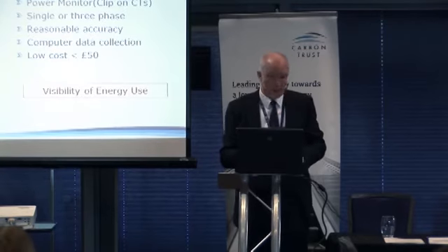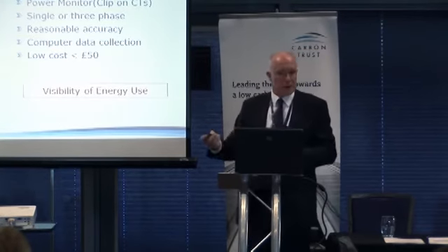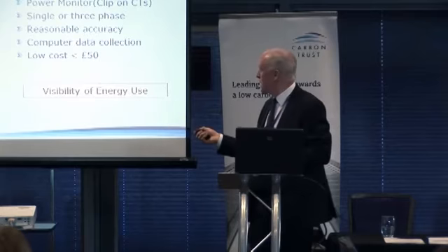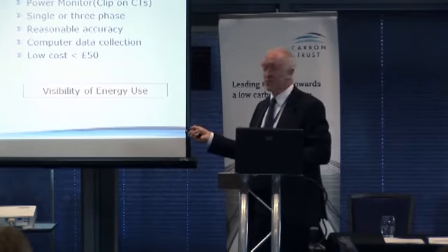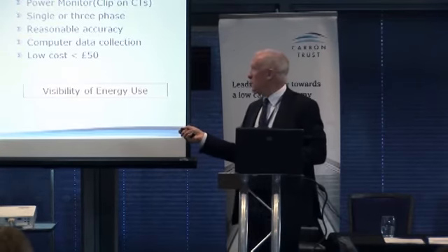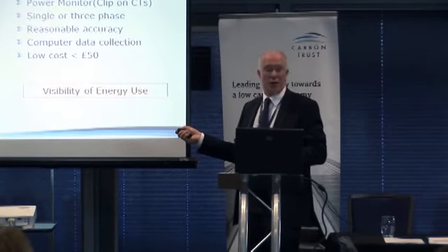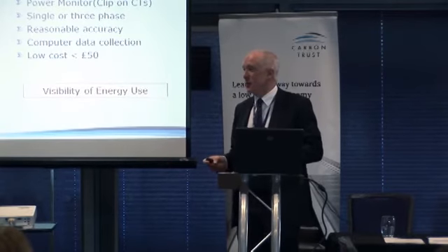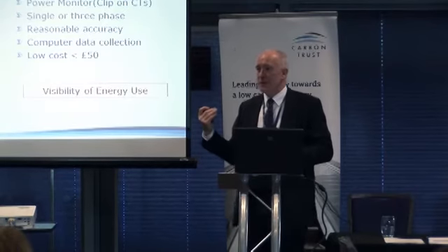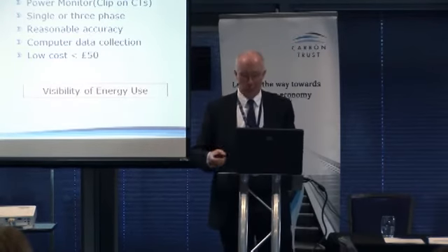As people are walking out, they can look at this, and they know from experience, having all tried to switch everything off, that this should be down at 864 watts. And if, as you walk out, it is at 2,864 watts, somebody's left a 2 kilowatt heater on somewhere, and you can switch it off before you leave. It's as simple as that. So everyone can act on this.